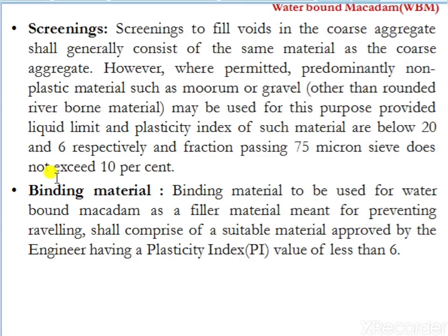Now let us see the next thing which is employed in waterbound macadam pavement, that is screenings. Screenings to fill voids in the coarse aggregate shall generally consist of the same materials as coarse aggregate.